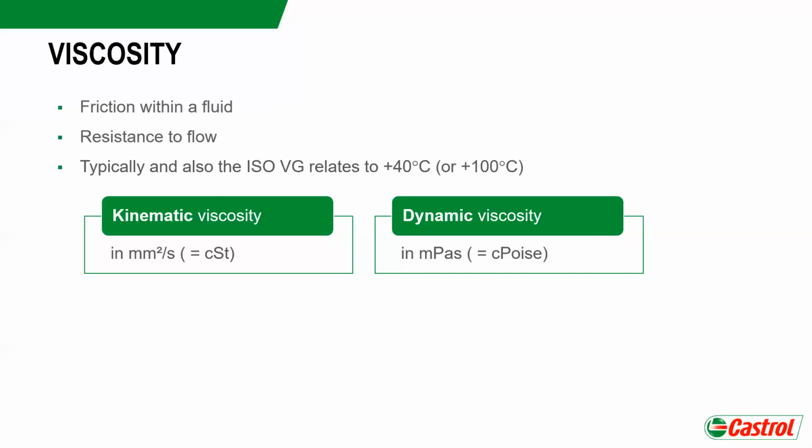Sometimes the dynamic viscosity is also needed. Then you only have to multiply the kinematic viscosity with the density of the fluid. But please be aware, you have to use the right temperatures for the density as well as for the viscosity. Next slide, please.